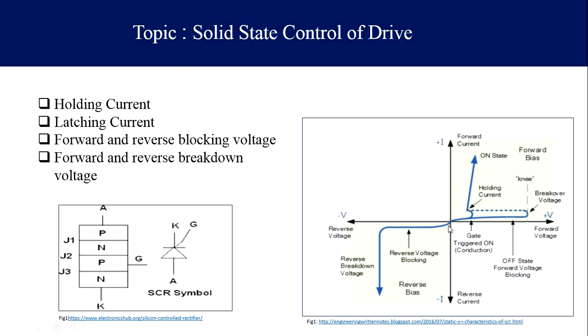That means, in this I will be having some reverse voltage as well as some reverse current, and this current will be mostly a leakage current. So, this is what is called a leakage current. Whenever I am applying some anode voltage in the negative, with a negative magnitude, then there will be some leakage current and it will be very small in magnitude.